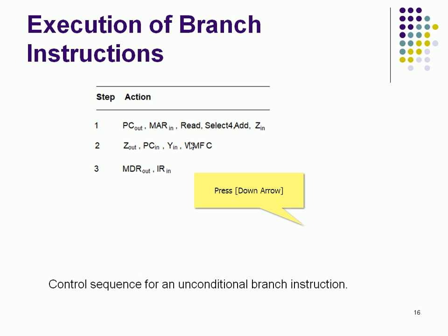From exploring the IR contents, we can understand whether it is a branch instruction, or an arithmetic operation. Here we are discussing the branch instruction, so let us assume that the IR holds a branch instruction. Then the branch address needs to be selected, and for that we have the offset field of the IR. After exploring the complete IR, we can understand the operation, operands and offset. So the offset field of the IR can be brought out and added to the earlier value, that is the PC value.